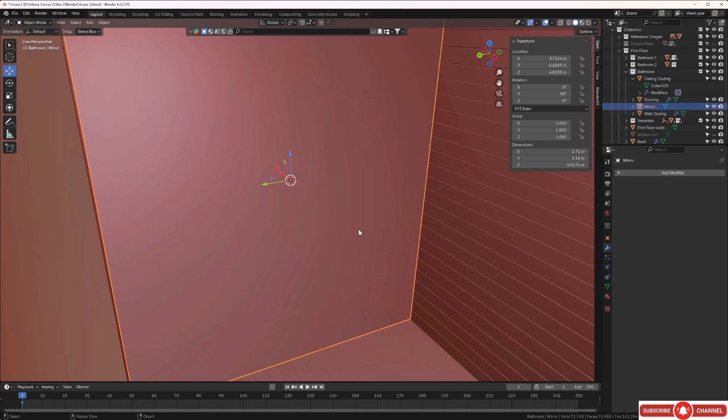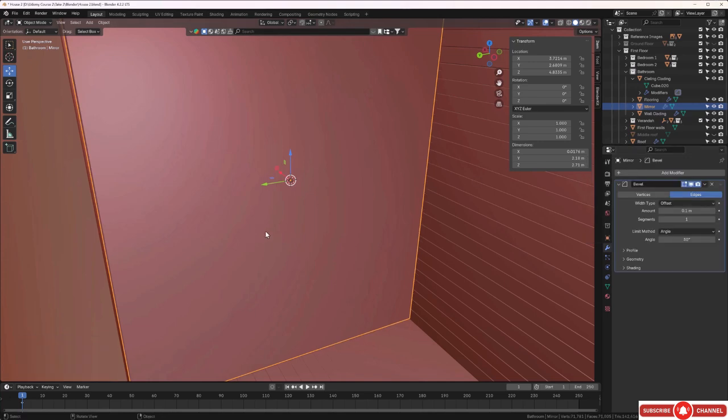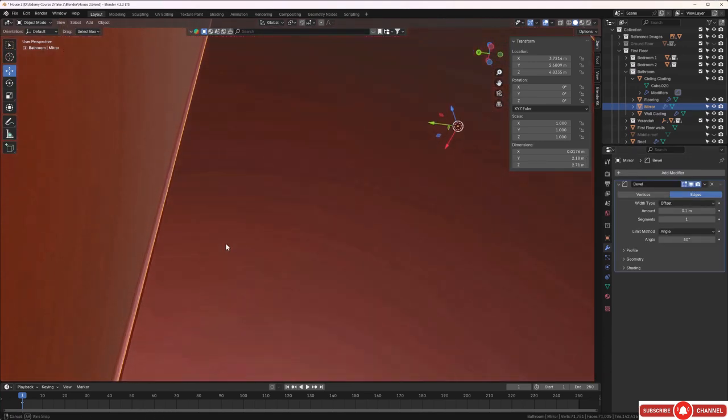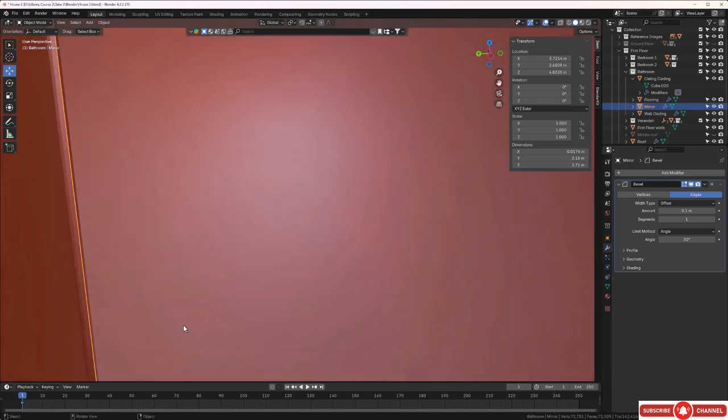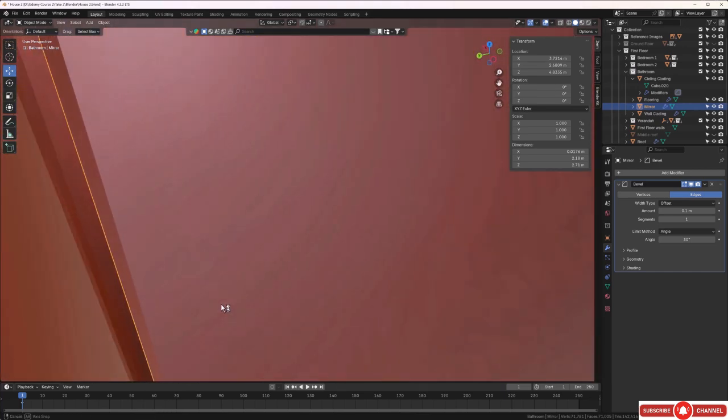And once we've done that, let's check the scales and the rotation's out, so let's press Ctrl A and apply rotation and scale. And let's add a bevel modifier to this. And let's have a look at that bevel modifier. And I'd say I'll leave that alone. I've got a slight bevel on that edge. Maybe it's too much. Let's increase this. Let's put an extra 0 to the right of the decimal point. Click enter. And let's go for another one.